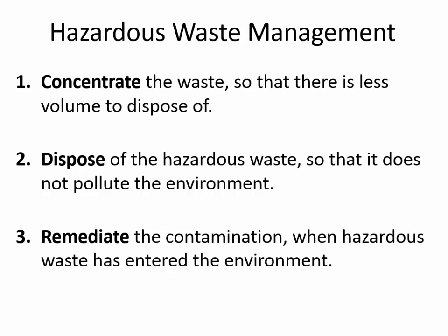So what we do in this management process is, as much as possible, we concentrate the waste so that there's less volume that has to be treated. And that principle of concentration is what they were doing when we visited the wastewater treatment plant. When they had the sludge in the drying beds, they could take the wet sludge to the disposal area. They could take wet sludge to a landfill. But when the sludge is 97 or 98% water, that's very non-economical. So by concentrating the waste, what they were doing is they're laying it out in a bed and just allowing the water to evaporate and leaving the solids behind.